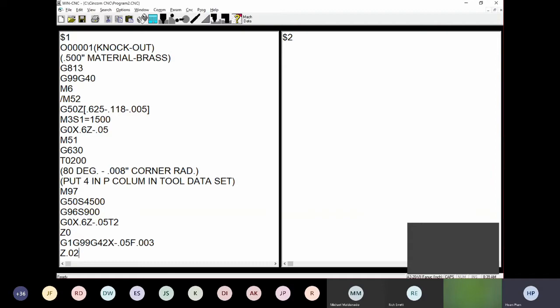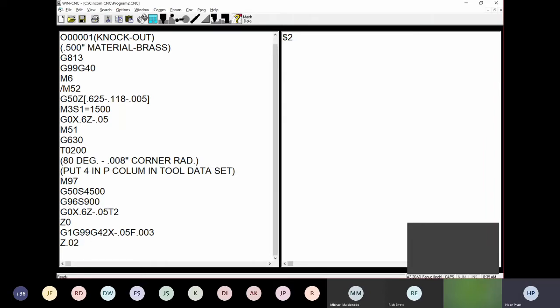And then after I'm done, I will move it out Z 20,000. Make sure, before I escape the tool, I will not leave any mark on the face of the part. And then after that, I can cancel the tool nose compensation. I can move it out to the top, and then I cancel the tool right here. So that means we finished the operation for the first thing, and then maybe we can put right here a note, just facing.